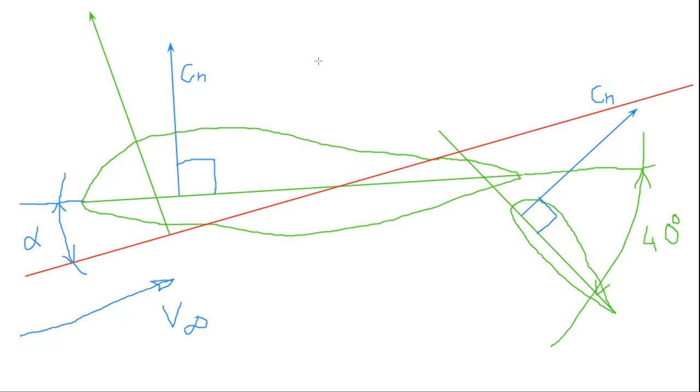So okay, we need to perform a rotation of these axes, and to convert our vectors we obtain from integration, we obtain two vectors, normal forces, first for the airfoil and second for the flap. And after we need to rotate this vector, and we obtain something like this. This is the lift part, and this is the drag part. And the same for the flap. This is lift for the flap, and this is drag for the flap.